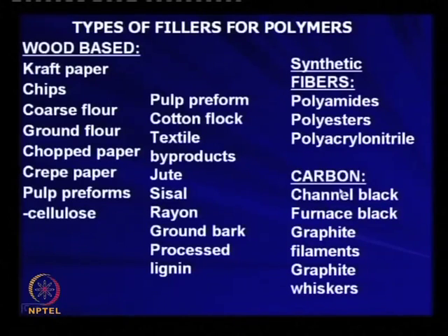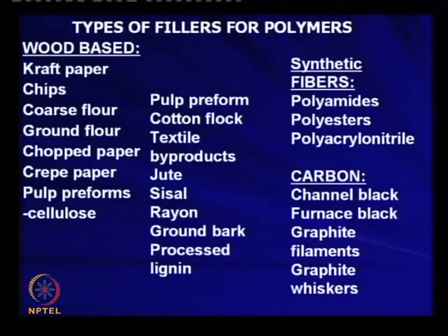Then carbon based fillers, you see carbon black, they are available in various grades. Say there are 3 major grades, channel black, furnace black and thermal black. Here only 2 are mentioned, channel black and furnace black, and thermal black is not mentioned here.